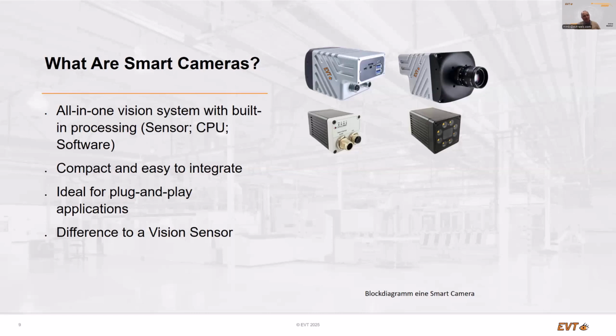So a smart camera is a very compact, fully integrated embedded system. If you remove the housing, you have an embedded system. With a housing, you mostly have a smart camera, either with the sensor in the topmost camera and the CPU inside, or in the lower one, you have the sensor, the light, the CPU, and of course the I/O system. Due to limited space, most smart cameras have limited I/O capabilities.